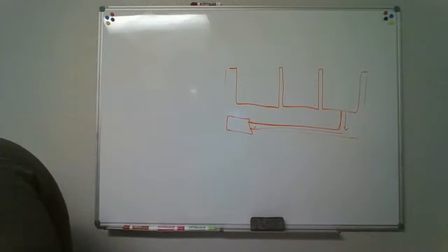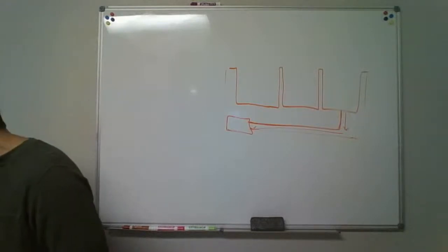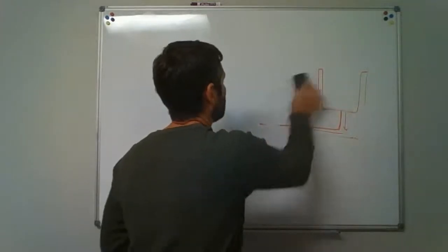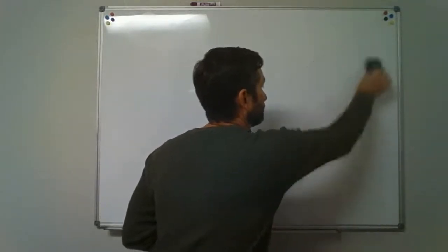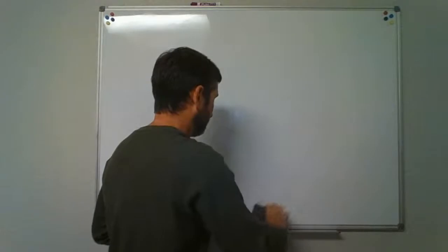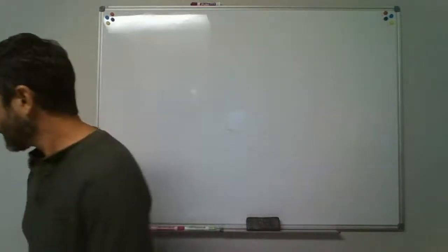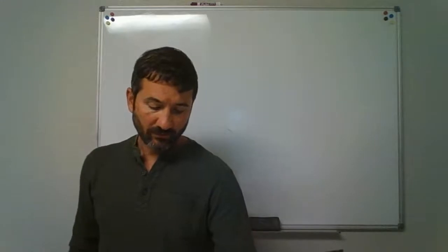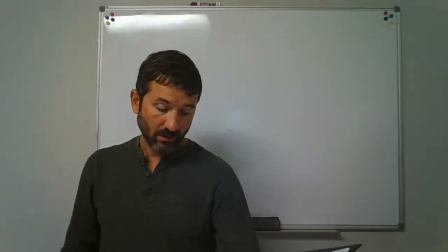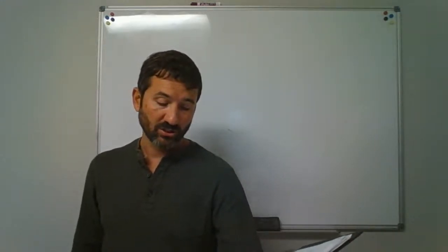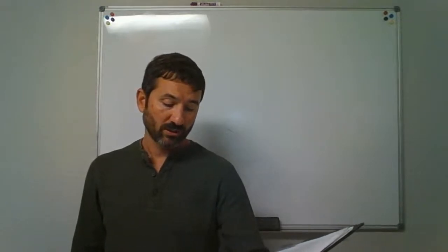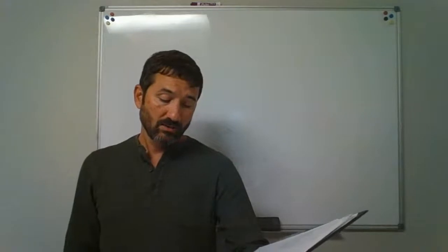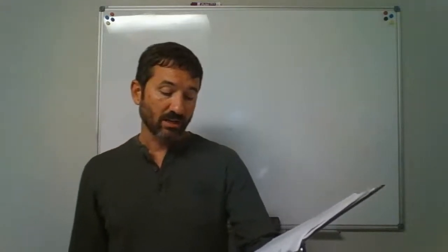Okay, let's see. Design of traps. Let's see what we have. The fixture shall be self-scouring, means self-cleaning out, not have interior partitions, except where such traps are integral with the fixture or where such traps are constructed of approved material that is resistant to corrosion and degradation.